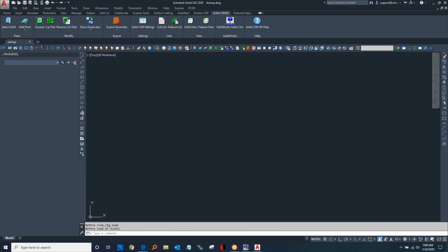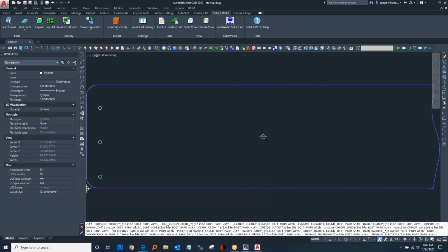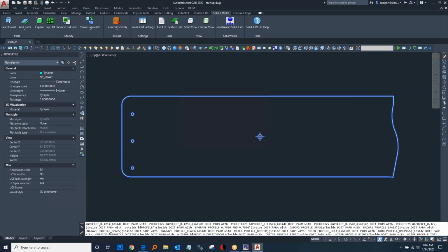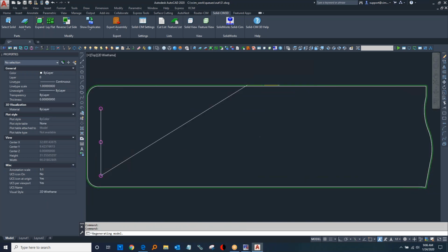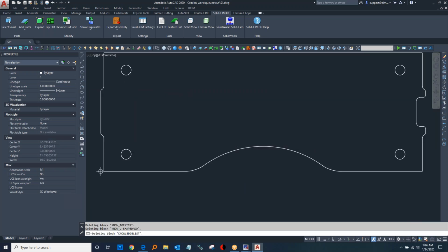We have advanced nesting features in SolidSim and RouterSim. We're going to do things like tool stay down nesting, or we could do common line nesting. We could do 2-sided nesting. We've got advanced small part hold down, so we have 2 levels of small parts, small and extra small. You could specify, for example, that the small parts have tabbing and the extra small uses an onion skin.